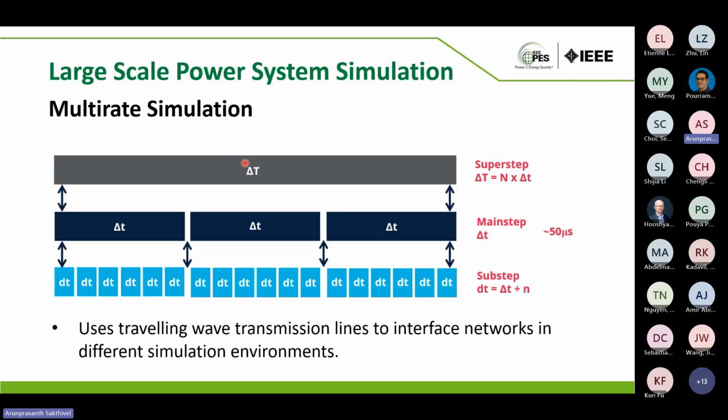And then we have a simulation environment called super step, which is a multiple of the main step, but still used to model the EMT simulation network. So these are the different time step environments. Depending on the system that we want to simulate, we could choose the simulation environment and then interface them to create a platform for large power system simulation models.